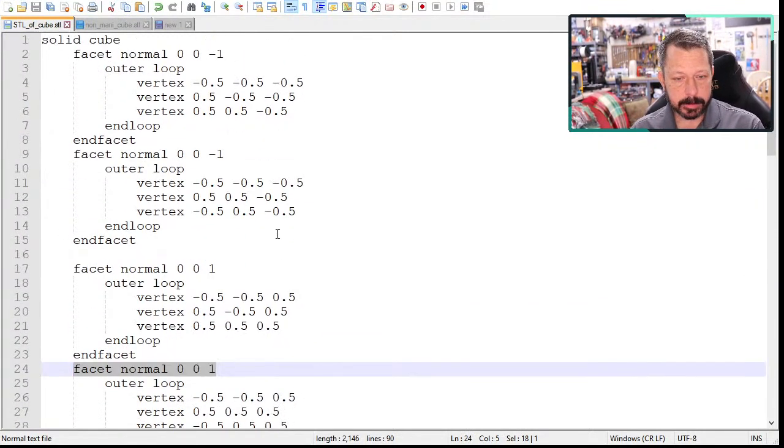So let's look at a non-manifold one, although this one could be considered non-manifold. Technically it's manifold, it's just the normals are facing the wrong way. Let's look at one that's definitely not manifold. Here we go. So this one is just totally missing faces. Now this looks like a thing that you could print, but you have to remember that these faces here have no thickness, so they only describe a volume when it's enclosed, like it's watertight. So here you could certainly imagine a part like this, but these walls would have some thickness.